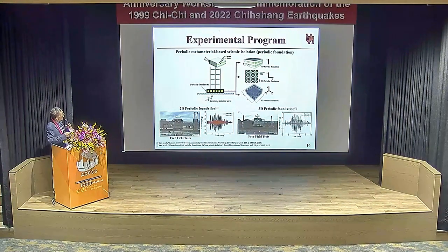And then we did the free field test with the strong support by Professor Stokoe. We did 2D metamaterial foundation. As you can see, we just cut this part, put here, and then at the top steel frame. And this is steel frame directly sitting on a concrete foundation. This one also sits on a concrete foundation, using Professor Stokoe's shaker to shake it. As you can see, for 2D, with the periodic metamaterial foundation, the vibration reduced to about 50%.